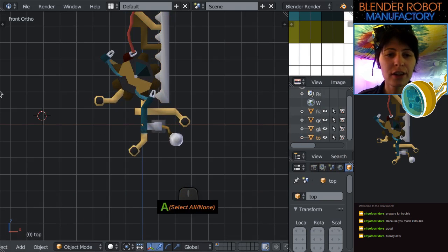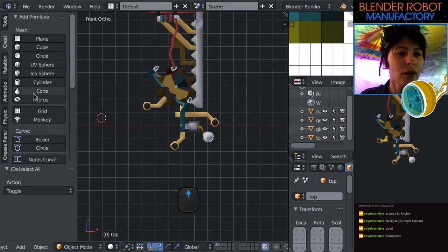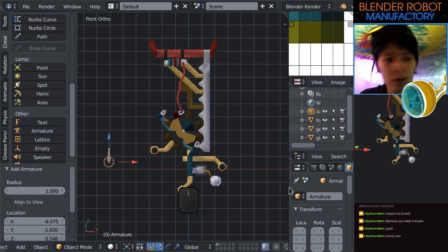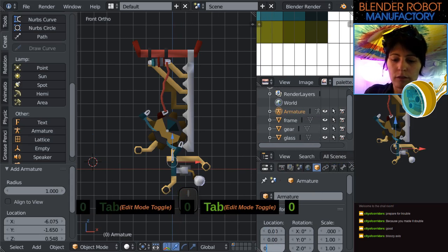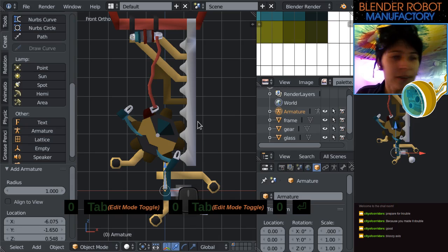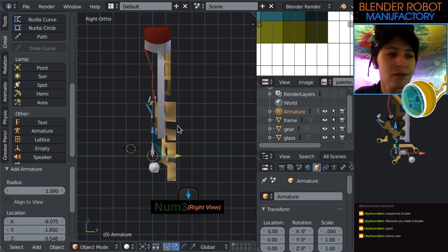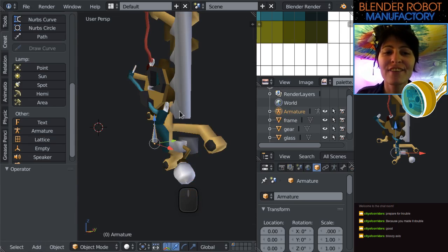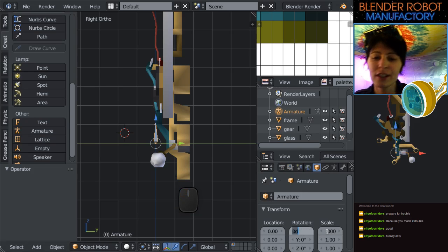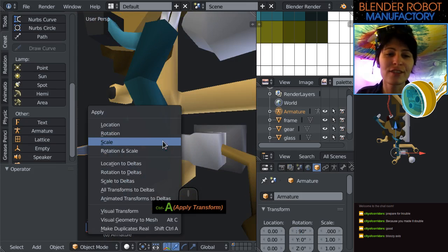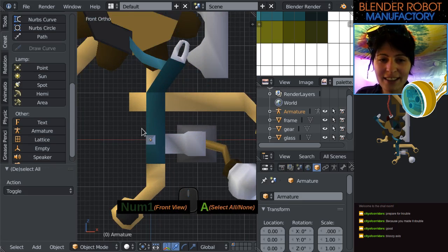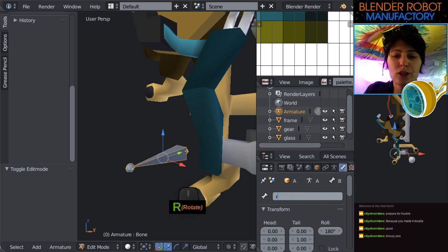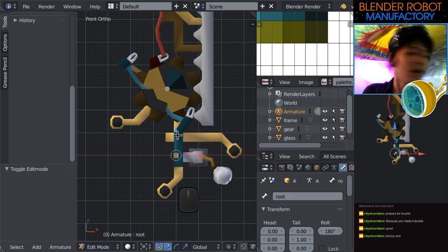So I'm just going to move these over a little bit, and in order to do that, I am pulling this out, going up, and in the Create menu, we're just looking for armature. There we go. I'm going to move this to the center of the scene. I'm going to make a root bone because Unity 3D always wants everything to be assigned to a bone, and it doesn't really like it if you have anything there that isn't assigned to a bone. So I'm just going to get that as unobtrusive as possible, apply the rotation, and that can just be our root bone. So I'm going to go into this, and I'll rename the bone over here in our bone menu to root, just to tell me that only stationary parts go there.